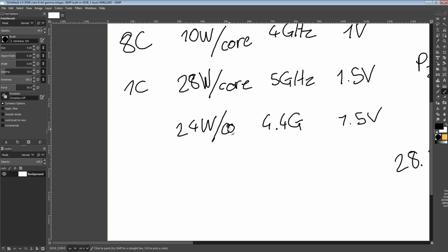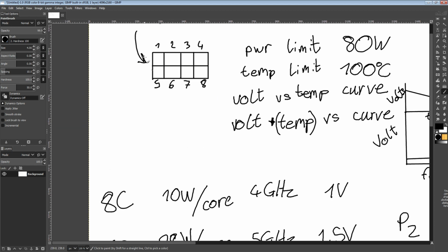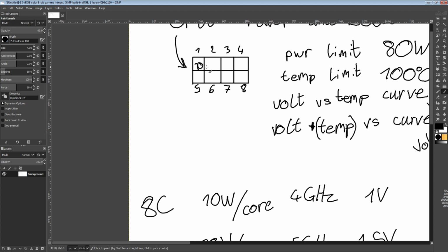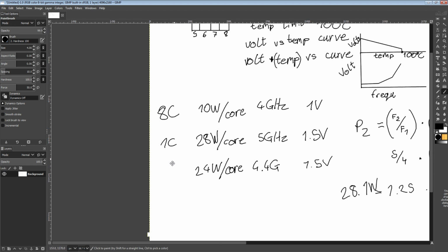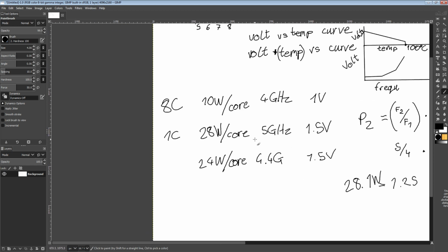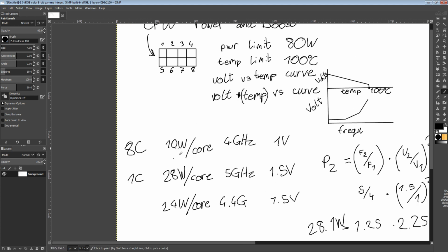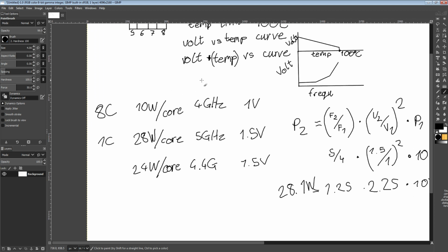Still very, very high, because instead of having 10 watts in each core, you're going to have 24 watts going off in one. That translates into very high single-core temperatures because you have a very high voltage. This is kind of boost algorithm behavior if you try to get your algorithm to absolutely max out the chip at any given moment.